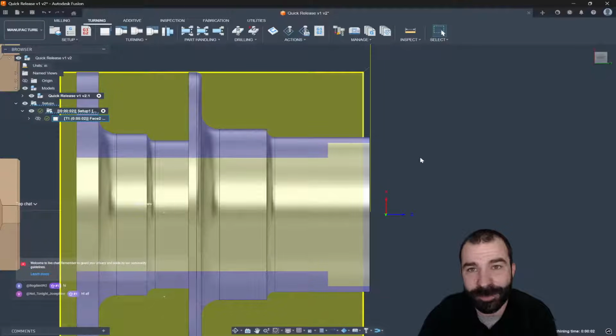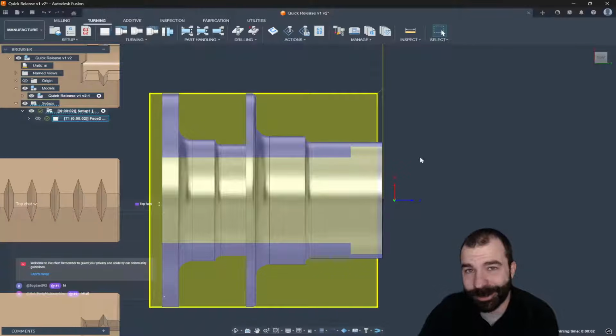The problem with that would be on this particular toolpath, we would be facing off the entire front of our part, which is why we don't recommend that you guys go in and change a bunch of stuff, which always leads me back to my rules. I know I didn't cover them this week, but we always want to work left to right, top to bottom. Fusion is going to help you guys a lot when we dive into the toolpaths later on.